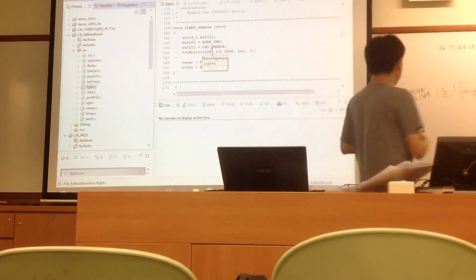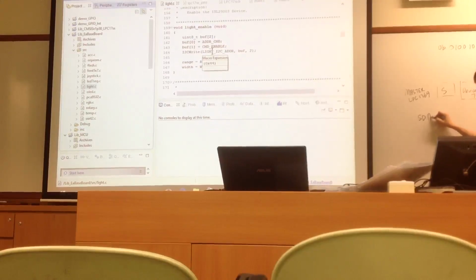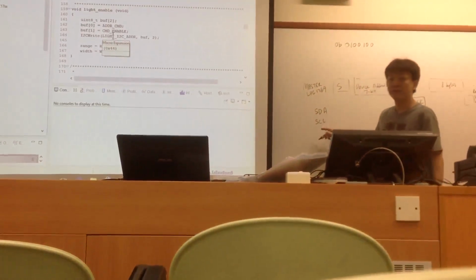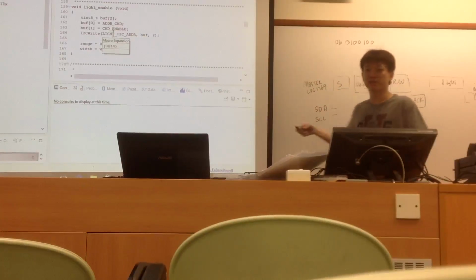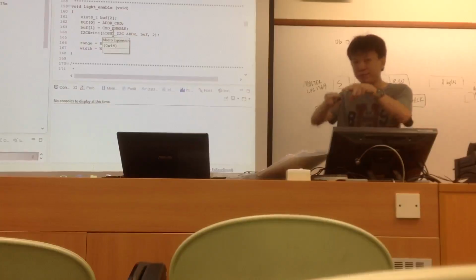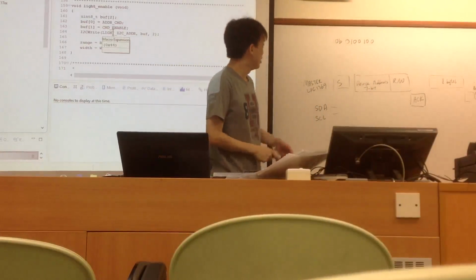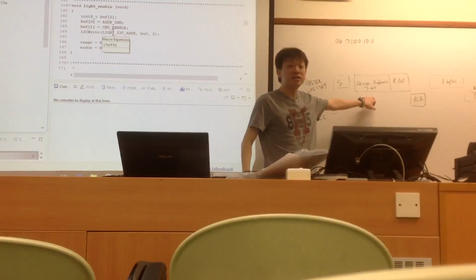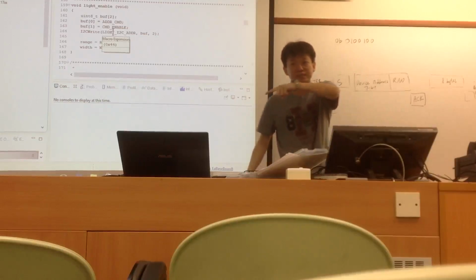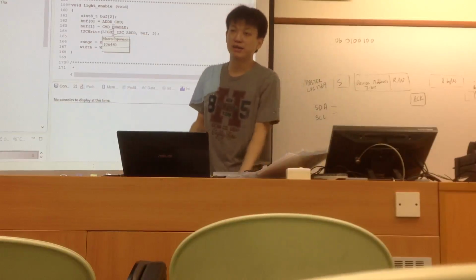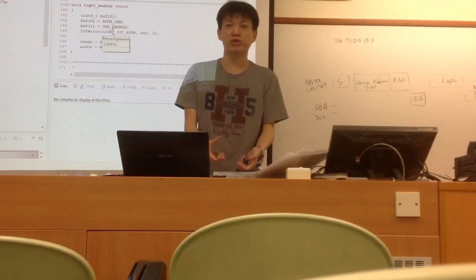The good thing of this I2C is they just need to use the SDA and SCL. They just need 2 pins. All the sensors, 3-4 sensors all connect to the same bus. Because every sensor has a unique address. Every time they will recognize this address first to decide this byte is sent to which device. Yeah. That's why you can connect a lot of sensors to the microcontroller.